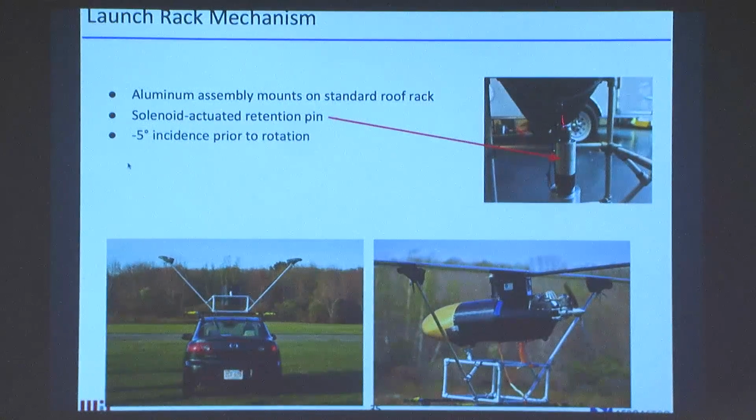In the front, we actually had a failure on our second flight. The airplane bounced out of the launch rack. We were taking off from a grass runway, and we hit a bump, and the airplane bounced out just below its stall speed. We were just barely too slow. So it was mushy and not very well controllable, and we had a hard landing or crash, which was fairly easy to repair, but that was definitely a failure of the system.